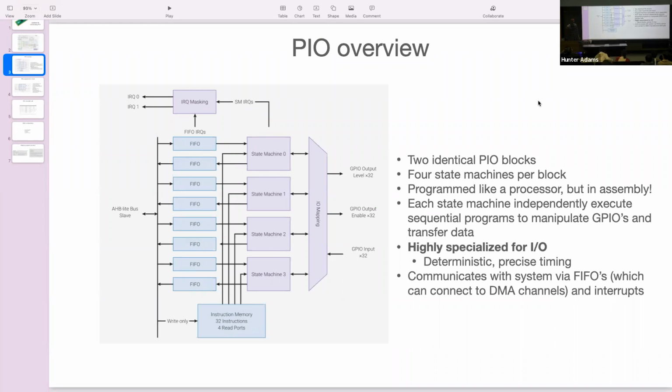The whole program that the RP2040 is running is all PIO programs communicating to DMA machines. These PIO programs are generating all the control inputs to this imager, all 30 of them at 200 megahertz, and it works. They can get the image off of it, which is exciting because an FPGA is like $400 and these are $1, right? So it's really exciting.